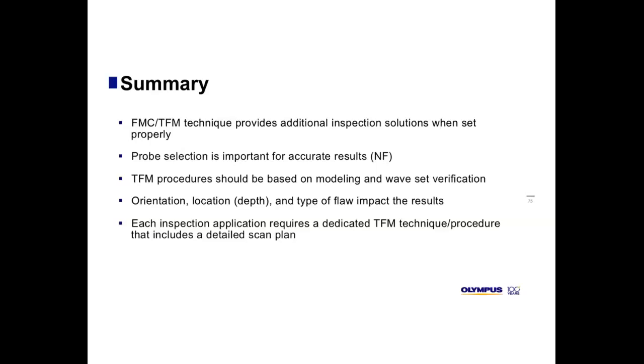TFM procedure should be based on modeling and waveset verification. This is very important. As we saw, if you use only one specific waveset, you can miss many indications because of their orientation or their nature. Orientation, location, and type of flaw impact the results. This is for sure a problem. However, it can be resolved with a good procedure and with a good modeler.